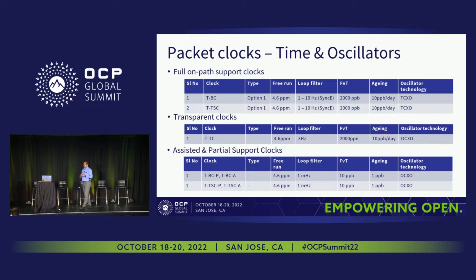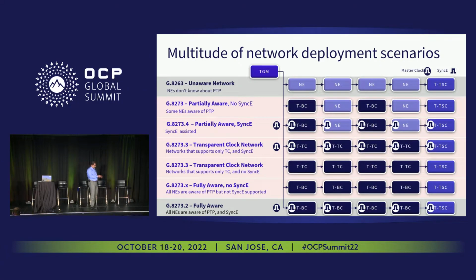But when we design a system, usually, taking a step back, you can see that some of these requirements need a lower level of stability clocks. Some of them need an intermediate level, and some of them need a higher level. So can we get into one oscillator specification that can meet all? Maybe yes, maybe not. But I'm trying to bring in one specification that can meet all the requirements, because when we design the equipment, we also have a number of deployment scenarios. So it needs to meet all of these scenarios.